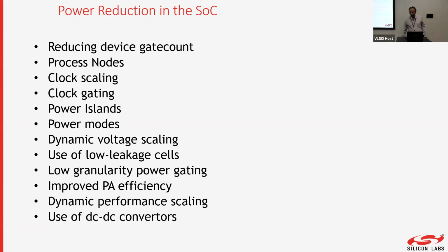Power is V square by R. The higher the voltage, the more power is consumed. So I want to reduce it. If I can do it with a smaller voltage, why not? There are pros and cons to changing voltage. We'll come to that. So voltage scaling, and the use of low leakage cells.